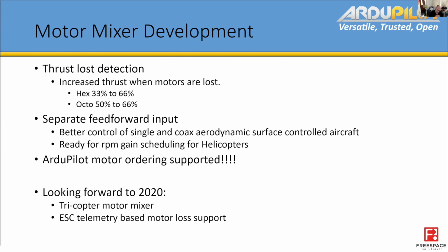The other big thing we did at the motors level is we separated the feed forward into the motors library. Now, plane and heli both already understand the significance of this, but multi-rotors have been somewhat neglectful of it because they don't actually require this feed forward in the rate. And this is particularly useful when your actuator output is approximately proportional to the rate of roll or pitch or yaw.